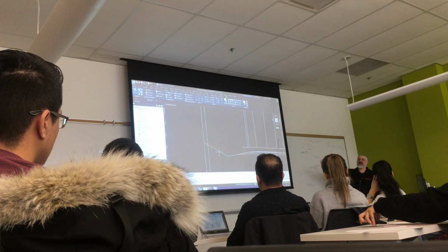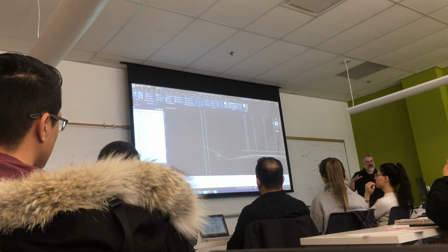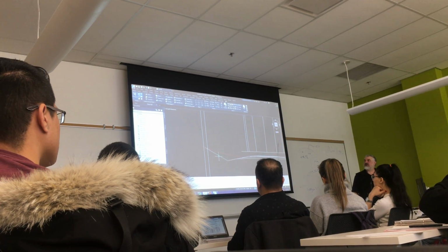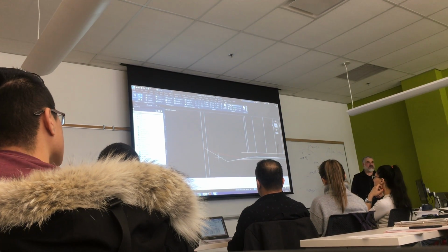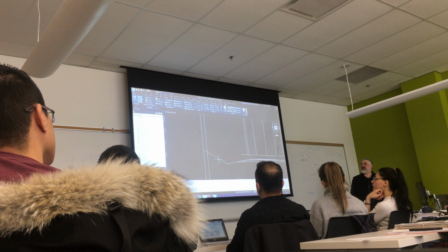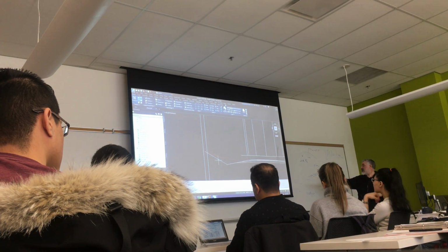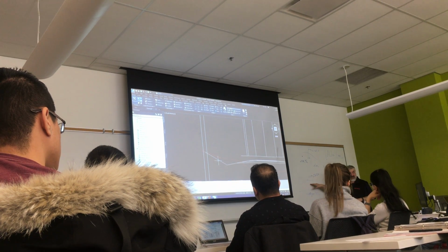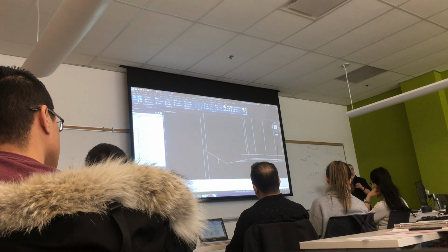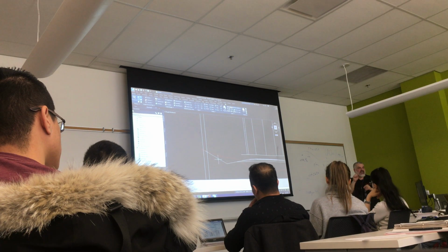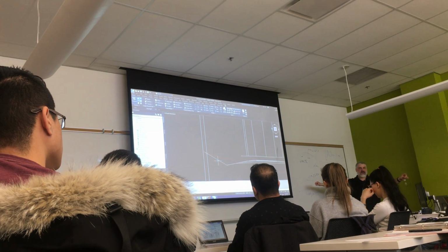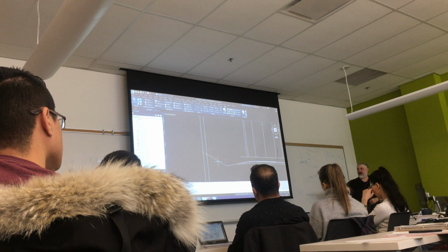Right? I'm going to accept that, close enough. I'm at least within the right of way. Yeah, I violated that 1 meter no touch zone, but I'll keep it for now. Okay? So these are the kind of things you run into. The fact that it's close is because when I do my original profile design, remember proposed versus existing, I try and match the existing as close as possible. If I'm close to existing in the center line, then I'm close to existing on the edges of the right of way as well. Okay, that's why it's pretty close. It's not perfect, but it's close enough.